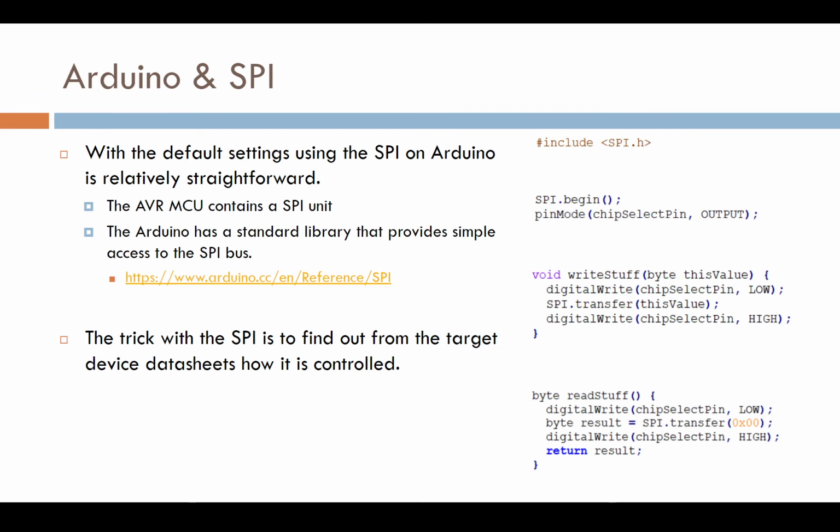Okay, then we have these buses which are defined between a microcontroller and a device, for example a sensor, like the I2C bus for sensors. There was the temperature sensor example where the hard part is to read the manual to see how the control logic actually works.